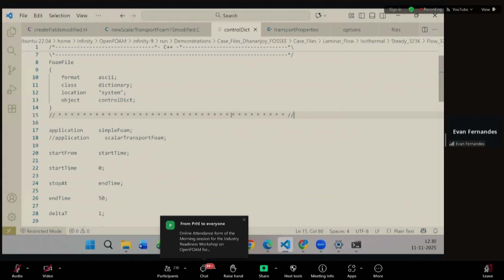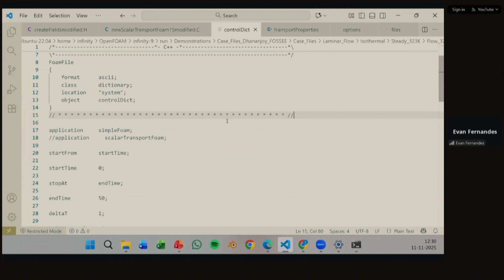For at least a beginner, it is too complex, but once you start learning OpenFOAM more, you will realize that for most of the solvers, whenever you're solving for additional parameters like these, you have to initialize your flow first, and then you can go ahead and solve the additional parameters that you require. So these are pretty much common once you start understanding OpenFOAM and CFD as a whole. So in our case, we will be solving first the flow equations, and then the temperature equations, and feeding that to solve the scalar equation.